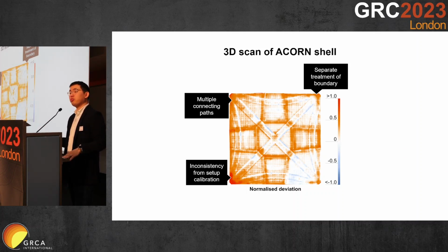The actual concrete sprayer itself is also tuned completely manually in the lab by technicians and myself, so there's some inconsistency in this setup calibration, especially the outputs, which results in variations between the segments. But all of these can be quite easily resolved, especially as we increase automation of the physical setup.